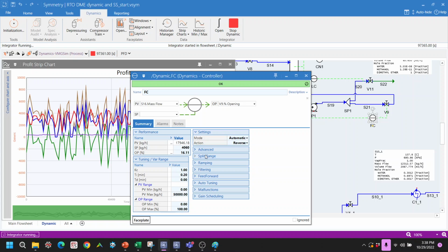This one is practically not encouraged, but since nothing is going to explode here, this is to demonstrate to you the steps to do this. It's not necessary that you have to do this. Now I reduce it to 4,000, and then the valve is closing. Valve is closing, to 6%. It was 4%, in such a way that it will then try to reduce the reflux flow rate. You can see.